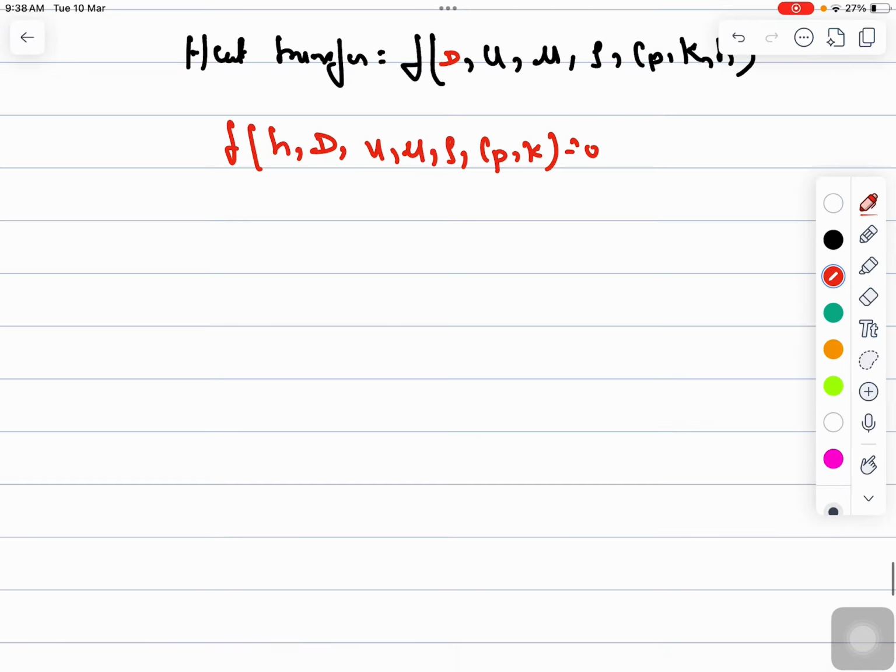So these are the different techniques. There are different techniques of conducting the dimensional analysis, right? The method that we are going to study in this lecture is the Buckingham pi theorem, and that is based on the fact that the functional relationship required to describe a system can be equivalently written in terms of n minus m dimensionless variables, n minus m dimensionless groups.